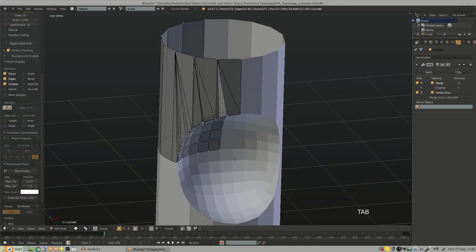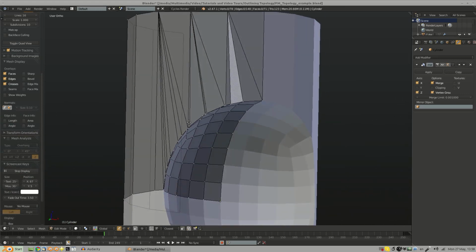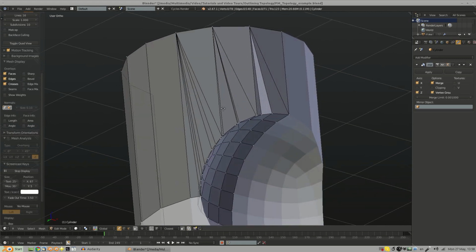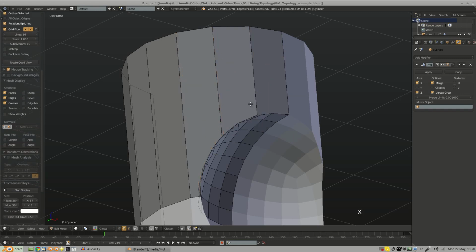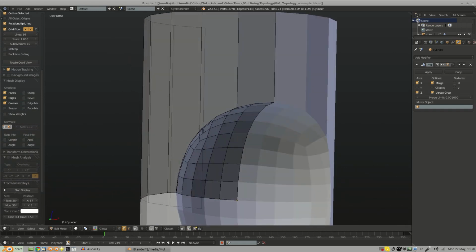Or not cheating, but it would kind of defeat the purpose. So the first thing I want to do is actually replace a lot of these with n-gons. So just select these edges, and I have to be in edge select mode first. So select these edges here, that one down there too, and these three, and I'm going to dissolve them, or limited dissolve. So it keeps the shape, but deletes the extraneous edges.